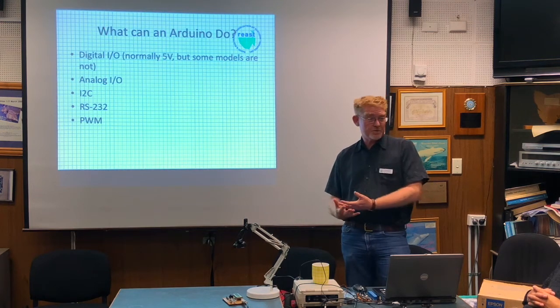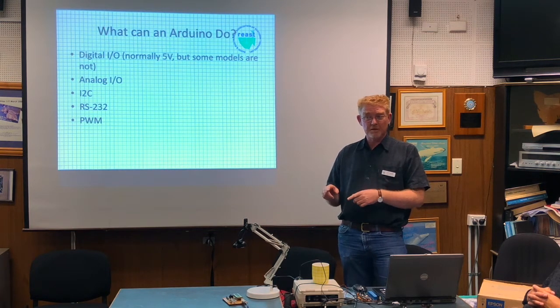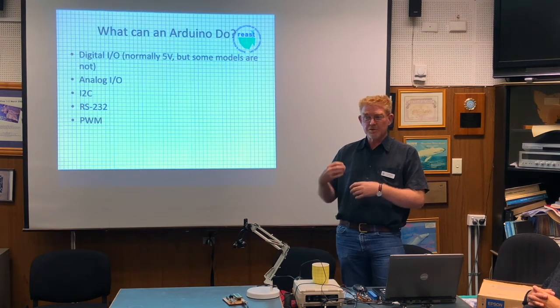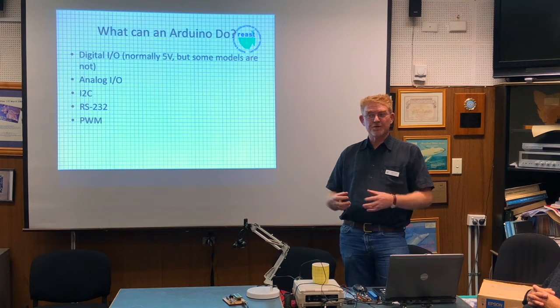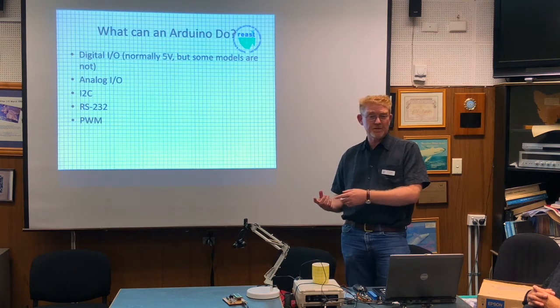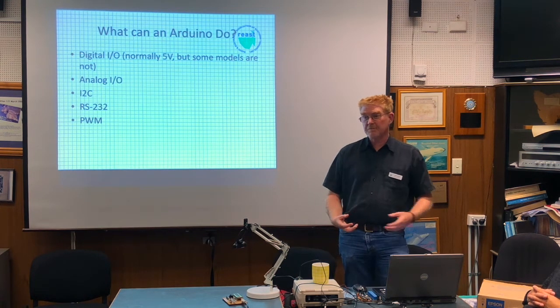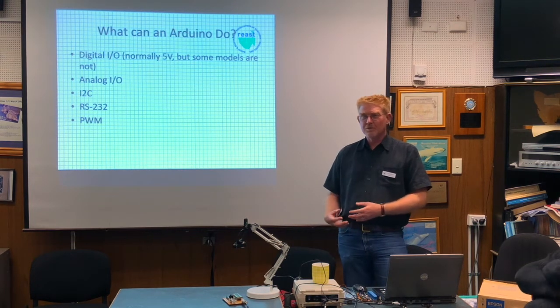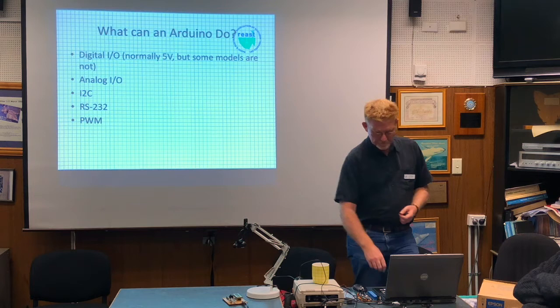It also does RS-232 on the chip, so it doesn't bit-bang like some processors. It actually has a proper UART, so it can form bytes neatly without consuming processor resources. So you can do serial I/O to your host PC whilst doing other things at the same time. It makes very good use of the processor resources, and your code looks like it's faster than it actually is.